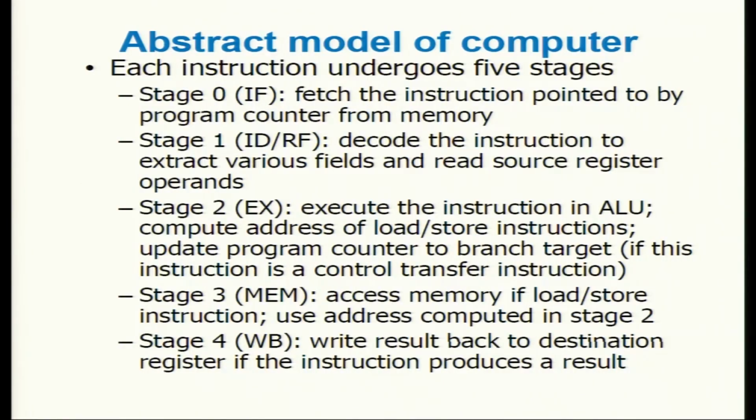Stage 1 is instruction decode and register fetch. So this is the stage where you decode the instruction to extract various pins and read source register operands. So this is where you read the sources and get ready for execution. Which is the next step, stage 2, execute the instruction in the ALU, that stands for arithmetic logic unit. Like it will have your adders, subtractors, dividers, multipliers and all.